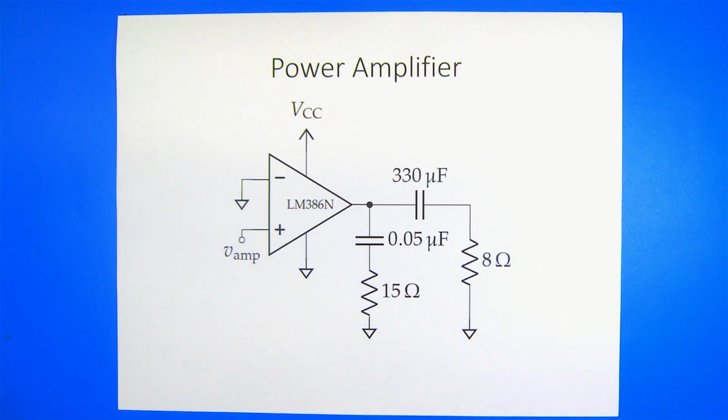The power amplifier subsystem provides the necessary power to drive the speakers. Within audio systems, the most common speaker impedances are 4 ohms, 8 ohms, or 16 ohms. So the power amplifier must be able to provide sufficient voltage and current to drive a small load. A single op-amp is not adequate to drive such small loads, so a purpose-built IC is used instead.